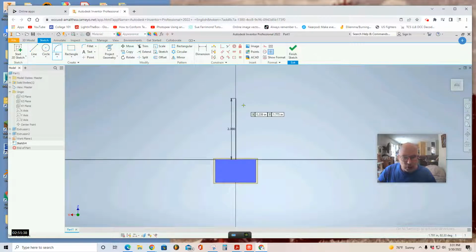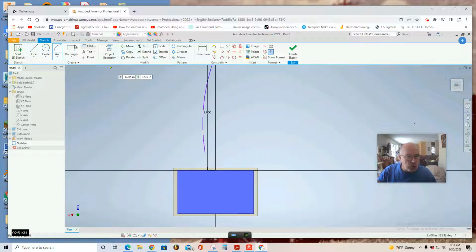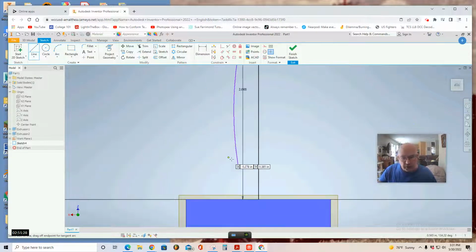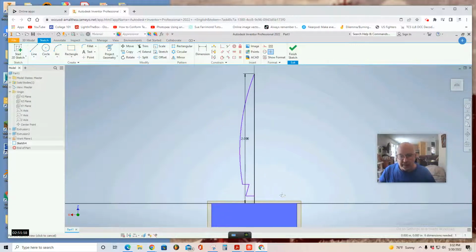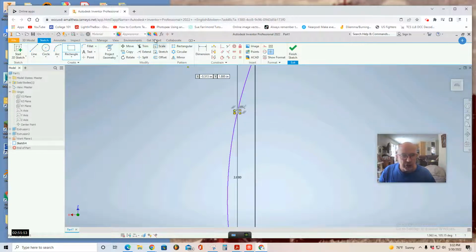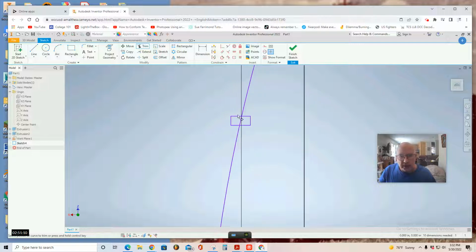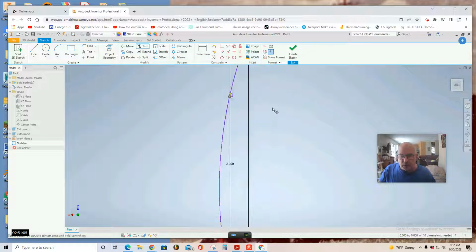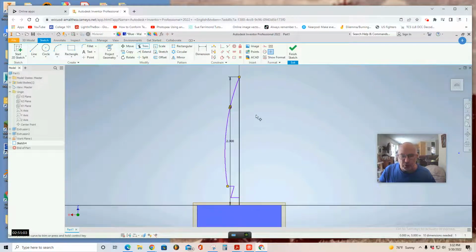I'm going to use my arc tool now to create my rocket fuselage shape. And I'm creating a bit of an arc for that retro rocket appeal. I'm going to use a shape like this to finish it off. I'm also going to use a little rectangle towards the top to give it that extra detail. Once you put a little rectangle up here, what I do is I trim these lines, and that will give you a little separation for your capsule.